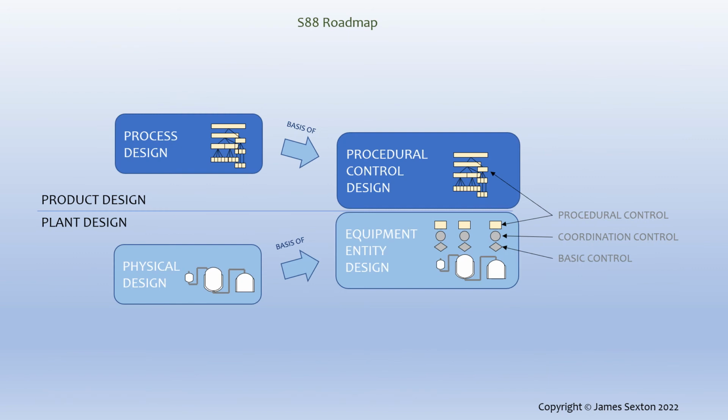So based on the examples in ISA-88, we see how closely related are the process design and the procedural control design. The first one defines what must happen, whilst the latter describes the steps to make it so. We've also described the place of the procedure in recipes and how recipe procedures execute. We have now discussed the 4 main models that should be customized to fully describe processes in a batch plant process cell. Now we need to understand the overlap between the procedural control design part and the equipment entity design to complete the picture.